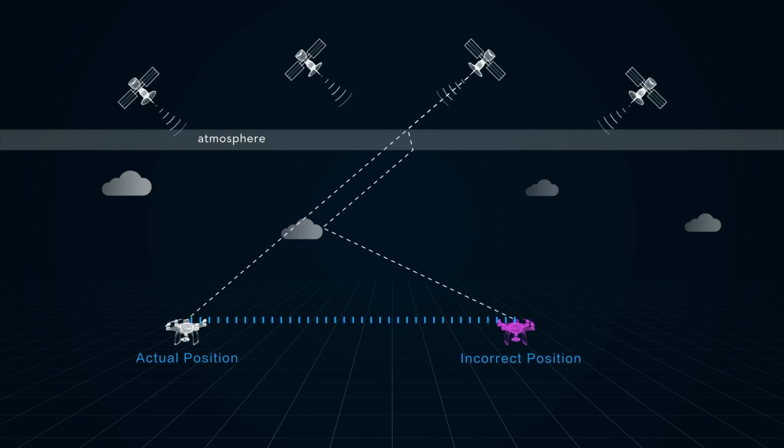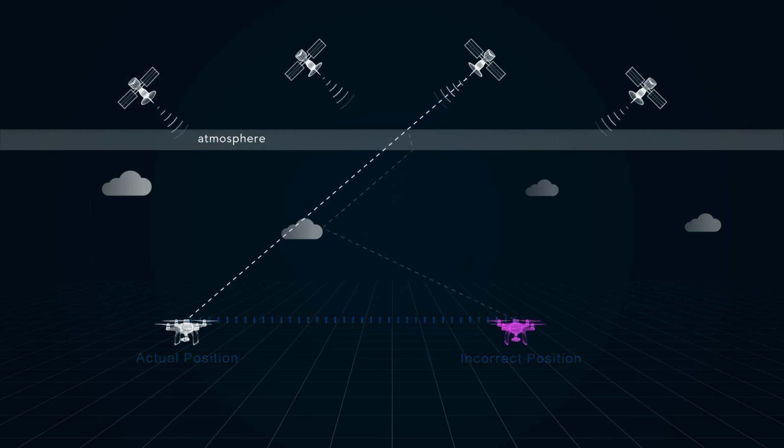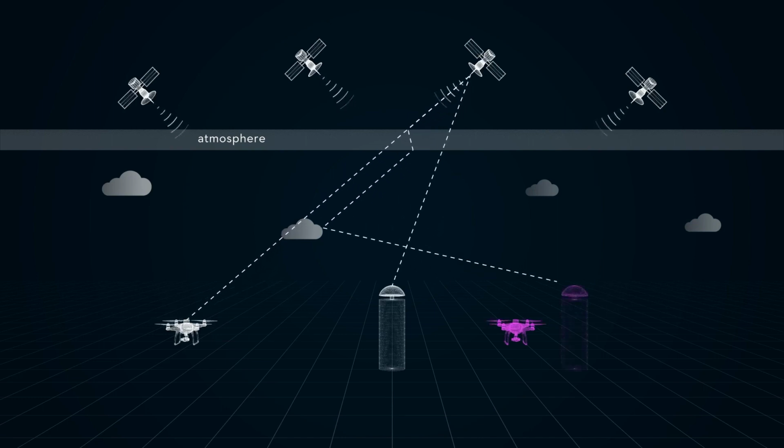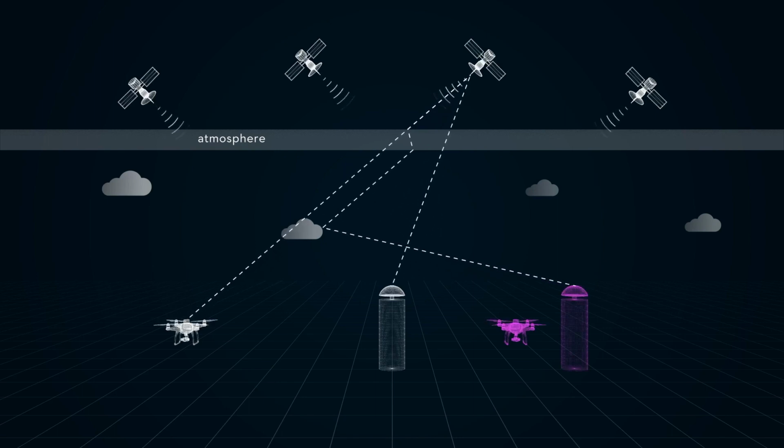How do we solve this problem? The answer is the differential positioning technology. This solution starts by setting a base station with a known position, then a connection through GNSS satellites to obtain a measured position of the base station. From this, the error between the known and measured positions can be calculated. Then, the base station can provide correction signals based on this error to correct other measurements.